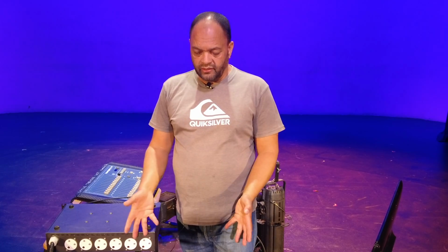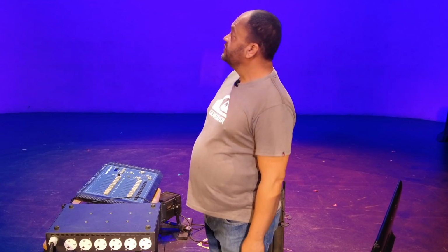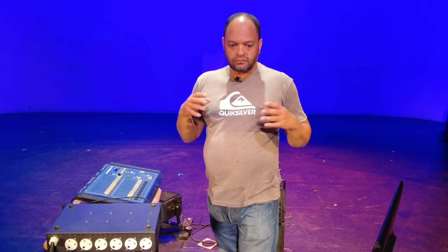So as a lighting designer, or the technician, you then set your scene accordingly. Bring up your light, depending on where you need it with moving heads. It's slightly different because everything gets done off the lighting desk, whereas with generics, it gets done in the pre-plotting session. What happens is you need to physically point that light into a position where you feel you will need it.